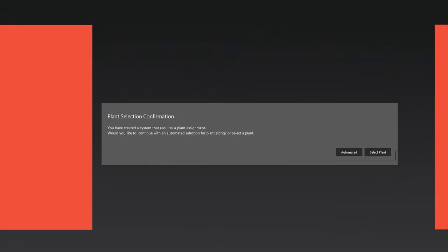If you select the Automated Plant option, the program will automatically create a purchased chilled water and purchased hot water plant in the form of district cooling and heating loops. The heating and cooling coils will then be automatically assigned to the correct loop, so nothing else in plants needs to be done in order to calculate the file for load design. Plants and loops will be discussed in further detail in Energy and Economics 101 Part 1, which is the third video in this 4-video series.